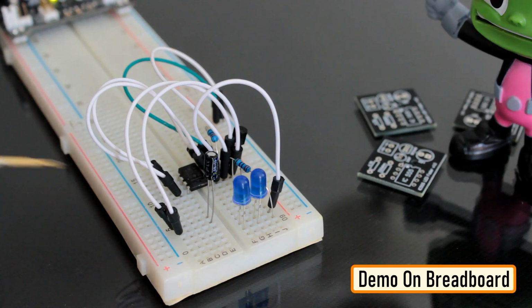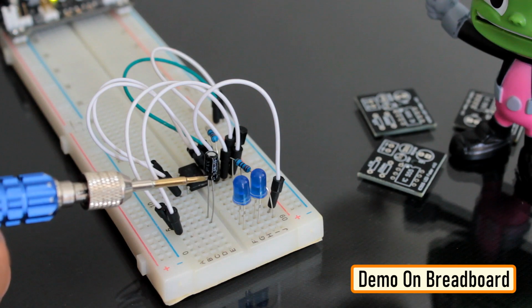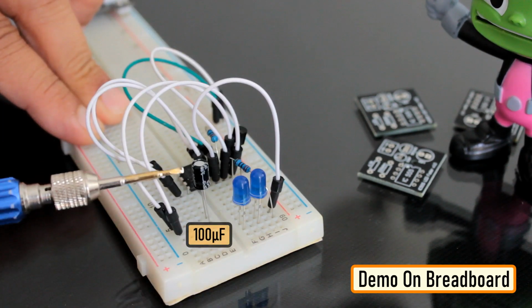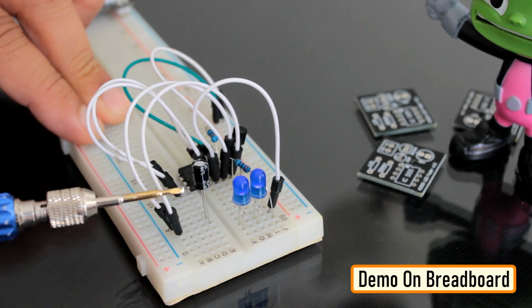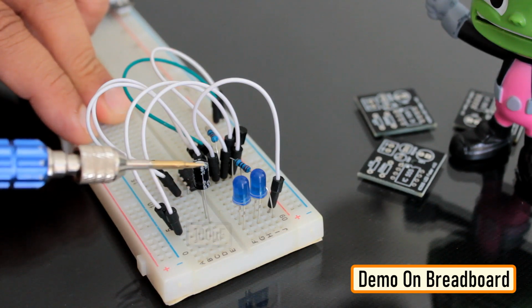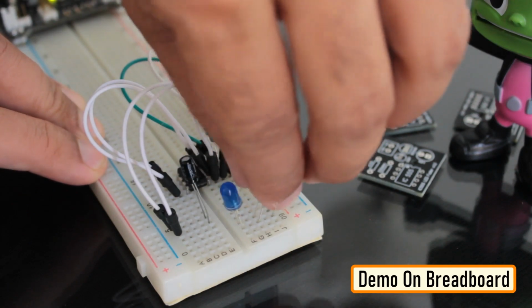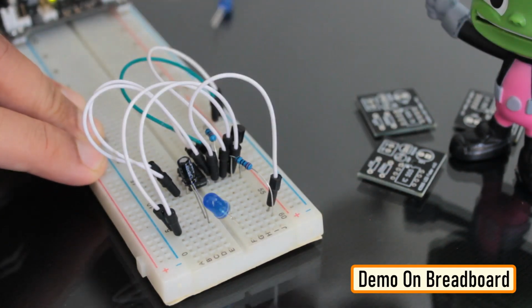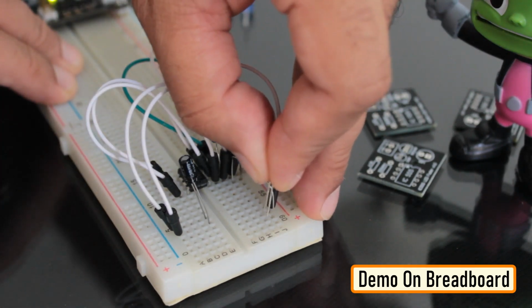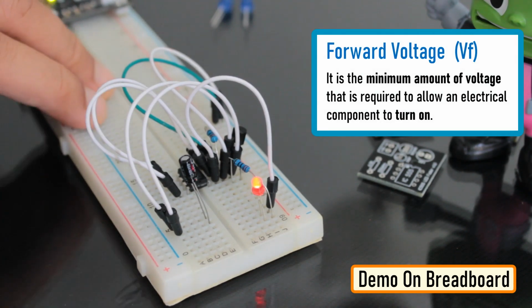So here is a quick demo on a breadboard. In the current setup, I have a 33 microfarad capacitor and a blue LED on the breadboard. Replacing the 33 microfarad capacitor with a 100 microfarad capacitor makes the LED fade in and out slower, as the 100 microfarad capacitor charges and discharges slower than the 33 microfarad capacitor. Also, by replacing the blue LED with a red LED, we can make the LED stay on longer than the blue one with the same value of capacitor. This is because the forward voltage of the blue LED is higher than that of the red LED.